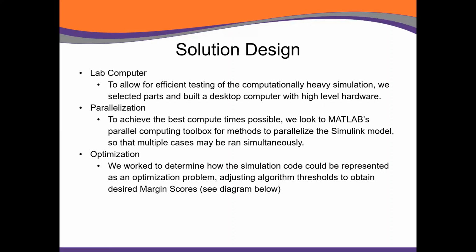Secondly, we focused on parallelizing the existing code. To achieve the best compute time possible, we took a look at MATLAB's parallel computing toolbox for methods to parallelize not only the MATLAB code, but the Simulink model, so that multiple cases can be simulated on multiple cores simultaneously.